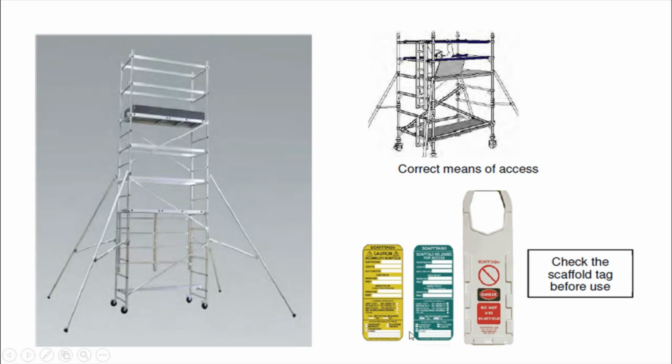But if this is on green status, that means the scaffold is safe to use, but you need to make sure that you are complying with safe procedure of using the scaffold. But if this is a red tag, that means no one is allowed to use such scaffold until it is rectified by the competent persons and the green tag is put on it.